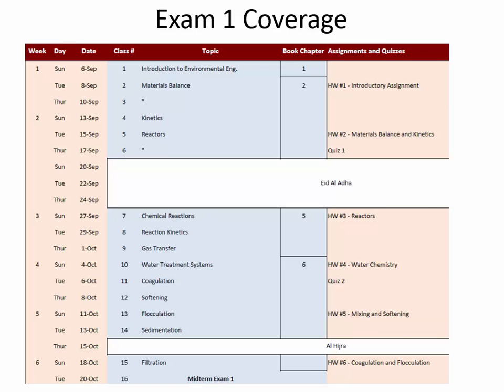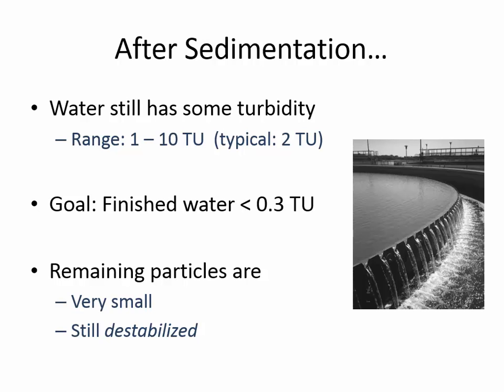That's what I'd suggest. Let's talk about what happens in water treatment after sedimentation. So we're basically just going through all of the treatment systems to take water that is turbid and making it clear. Remember that the whole point of sedimentation was to remove those flocs. We were talking about circular particles that settle downward, and why is it that we want them to group together?